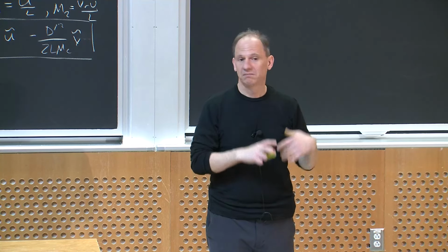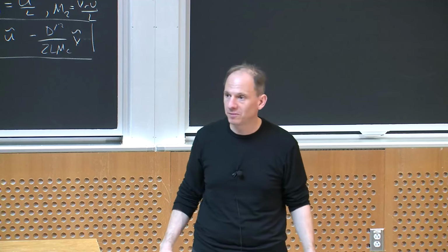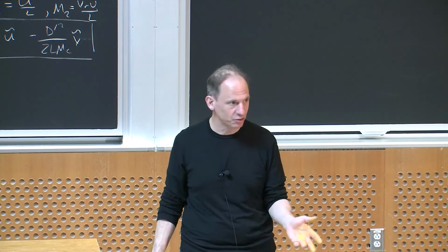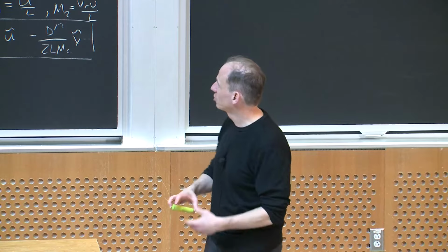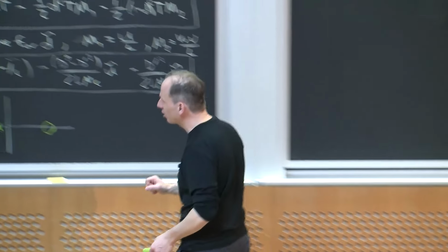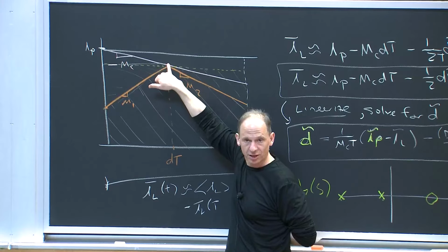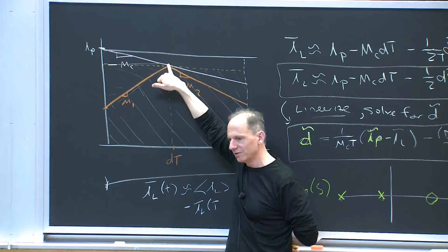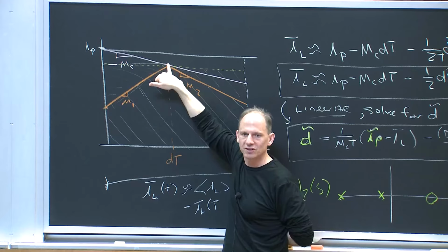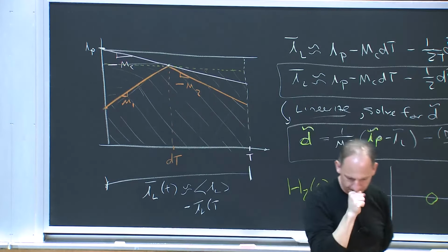And in fact, if you're designing most kinds of PWM DC-DC converters, most of the control chips on the market are going to use current mode control. This version that I'm showing you is called peak current mode control because you're controlling the peak of the inductor current. And that's the most common kind. There's also valley control, and there's a few different versions of this general idea, but this is the most popular one. Okay?